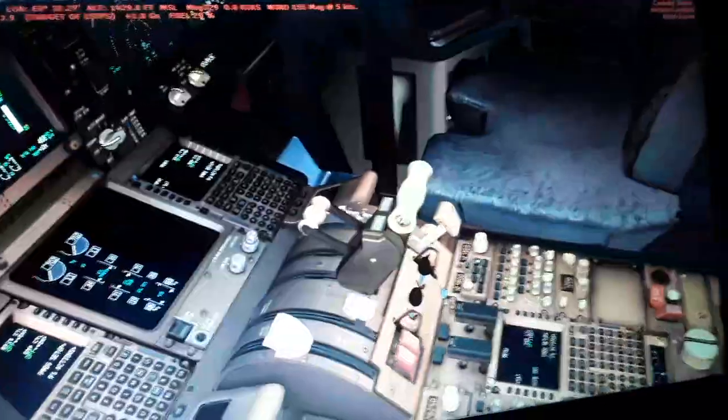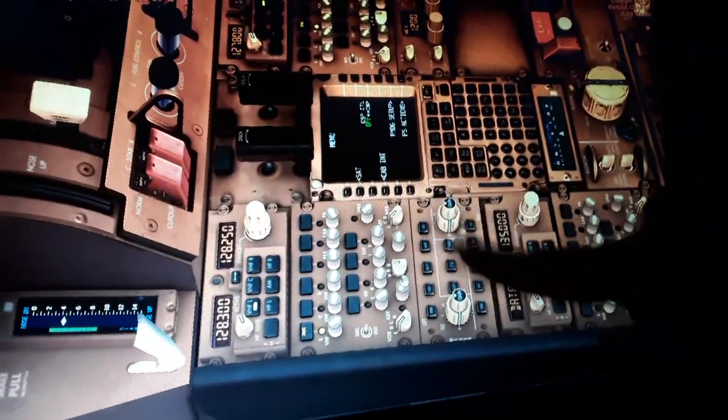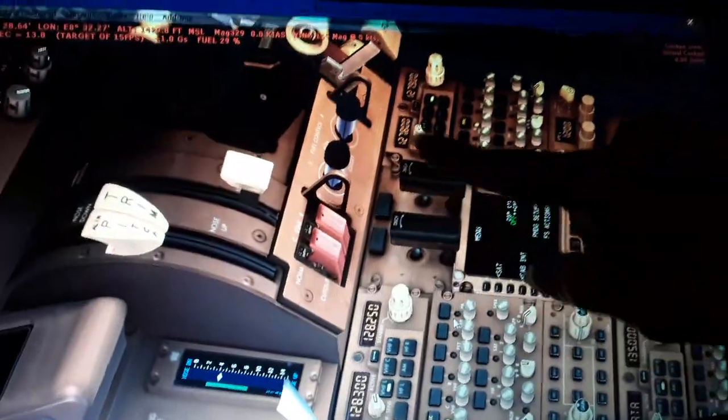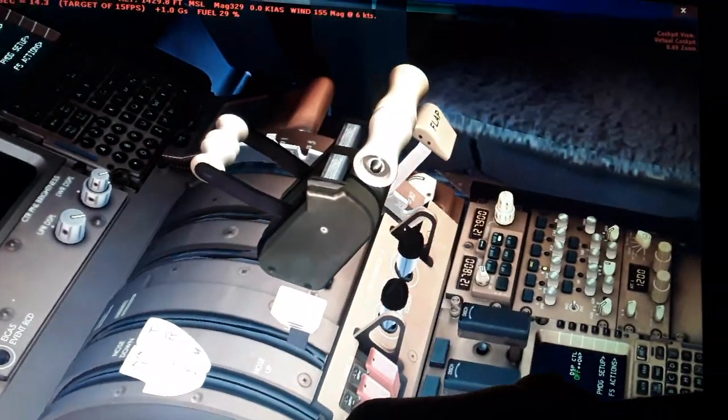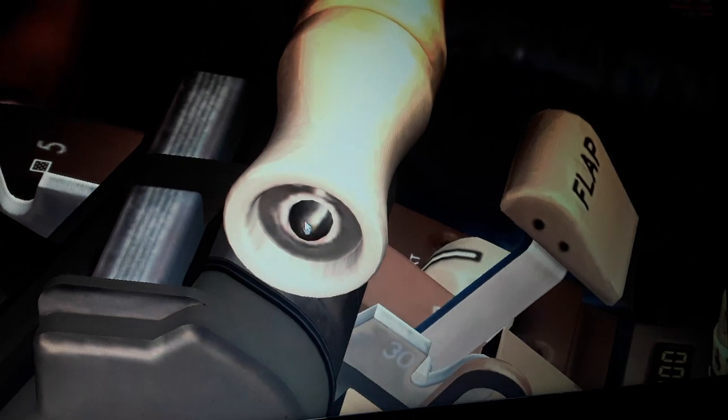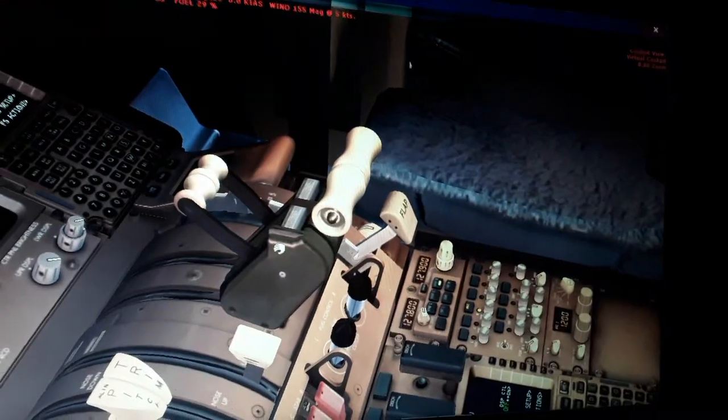I will show you the rest around the flight controls, also the thrust levers, the weather radar, terrain radar, radio communication panel, the fire extinguishers, left and right engine, the fuel flow to the left and the right engine. I told you the speed brakes, then retract, flaps, up, down, takeoff, go around switch. I told you the auto throttle over here: connect, you have the auto throttle, and you take manual control of the engine. Press this switch over here, the takeoff, go around, and the thrust reverser for the engine.